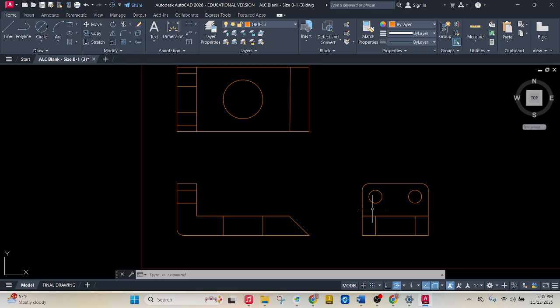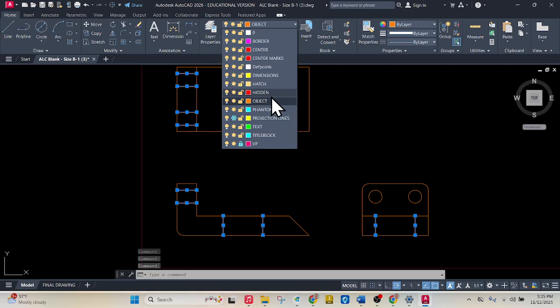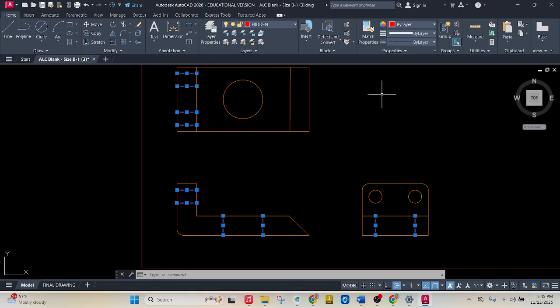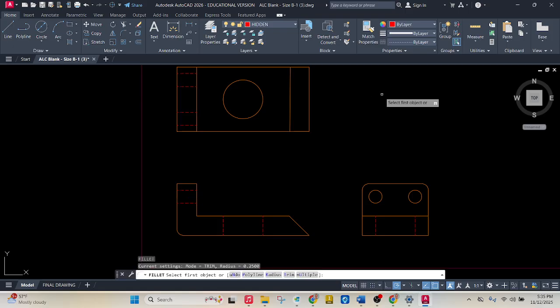And then we got to change our line type. So we've got these lines that are supposed to be hidden lines. So if I click on them, it'll multi-select the lines, which is nice. Click all of these. I don't have to hold shift or anything like that. I just click them. And then under where it says the line type, I'm going to change to hidden. Click there, hit enter, and now all of those are going to be hidden lines, which is really nice.